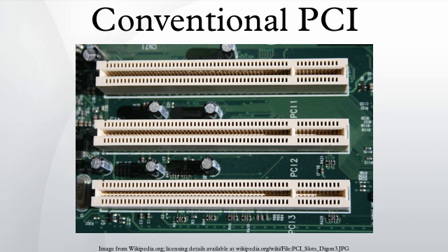SBO# and SDONE are signals from a cache controller to the current target. They are not initiator outputs, but are colored that way because they are target inputs. PME#, Power Management Event, is supported in PCI version 2.2 and higher. It's a 3.3V, open drain, active low signal. PCI cards may use this signal to send and receive PME via the PCI socket directly, which eliminates the need for a special Wake-on-LAN cable.